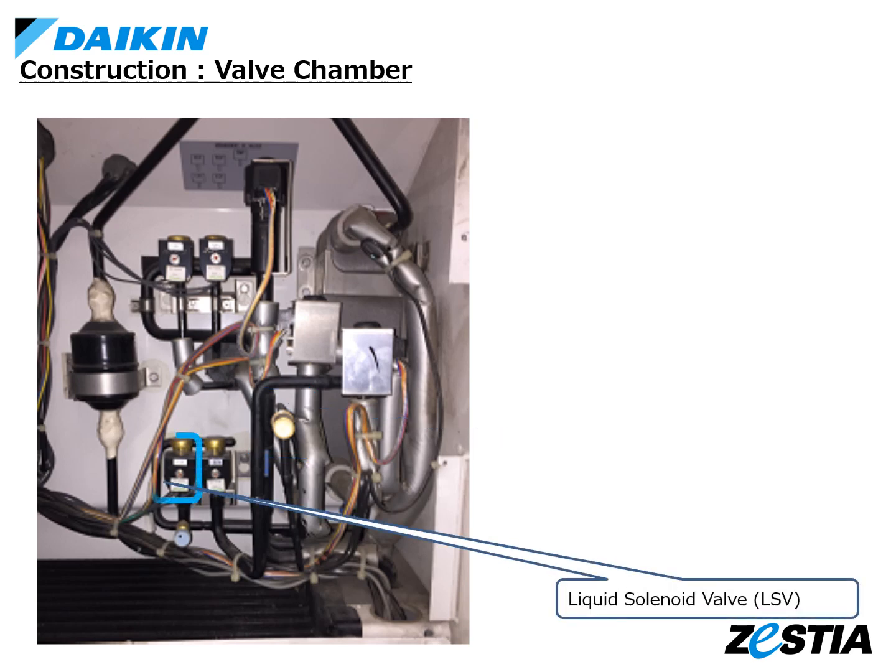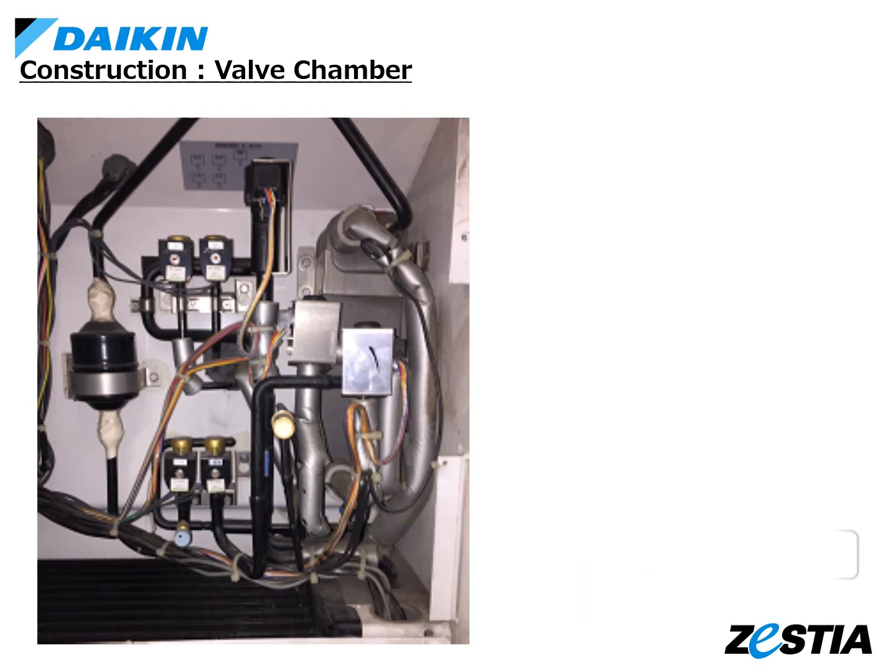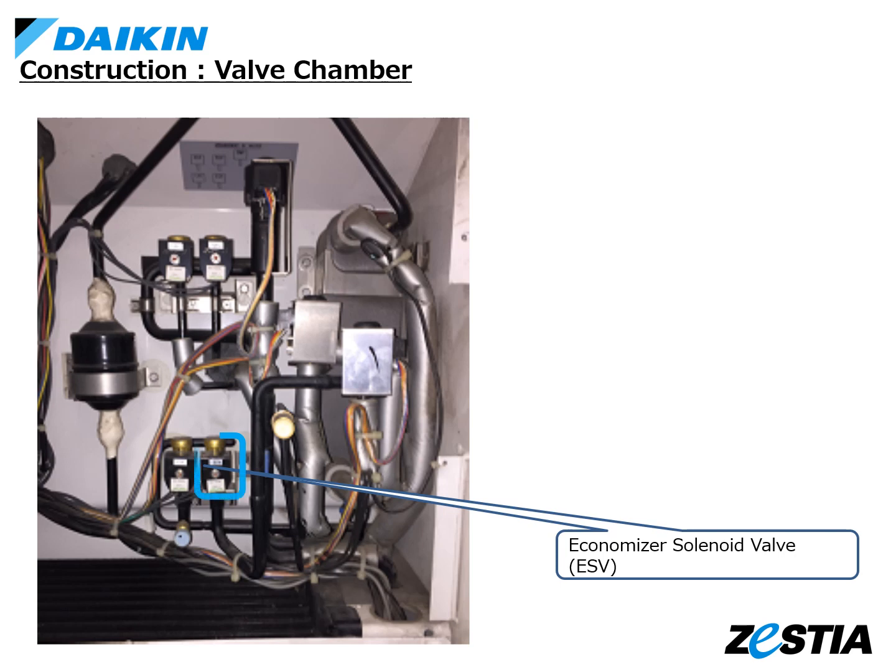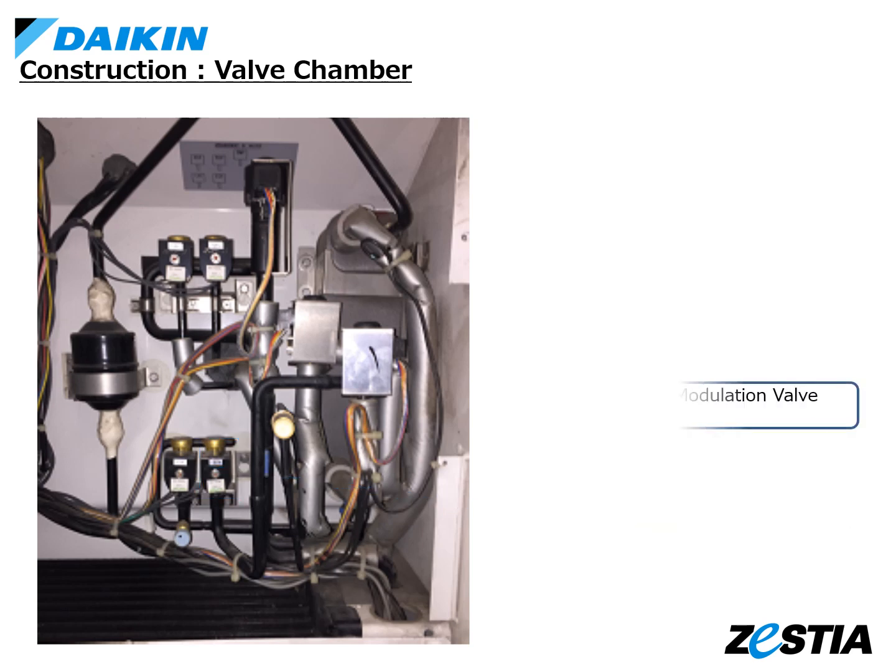LSV is opened when the compressor is in operation. It will be closed during defrost, heating and pump down. ESV opens in combination with the EMV, in pull-down and full cool operation. EMV controls the refrigerant quantity through the economizer and pull-down. Controlled by the eco-in and eco-out sensors.